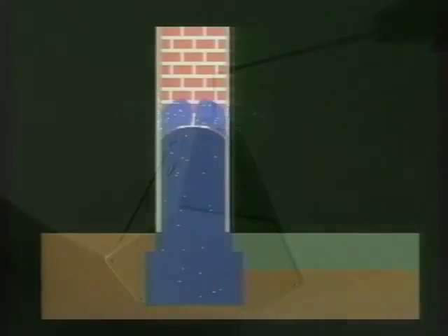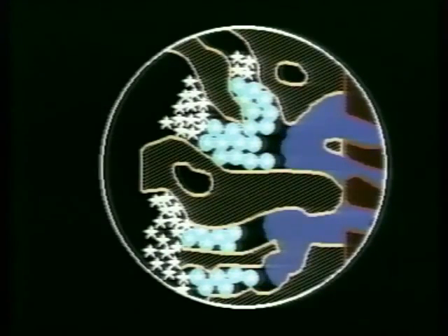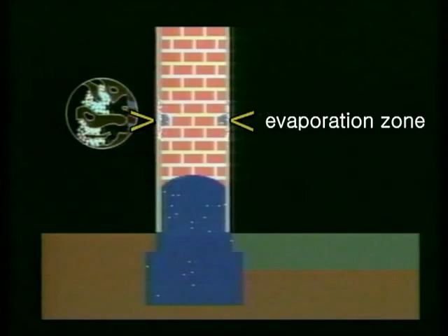This is not the case when the Aquapol method is used. Only the upper part of masonry moisture evaporates. The much greater part moves downward into the porous capillary system of the wall. This reduces the drying out time by half. Dissolved salts come out in the upper evaporation zone and the larger part moves back to the ground where it came from. The evaporation phase takes about 3 to 12 months. You should ideally wait for this length of time before starting renovation of plaster.